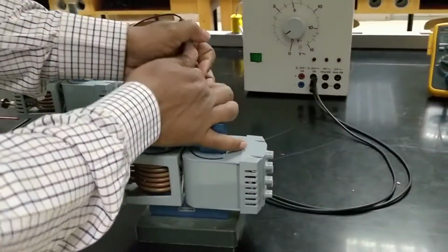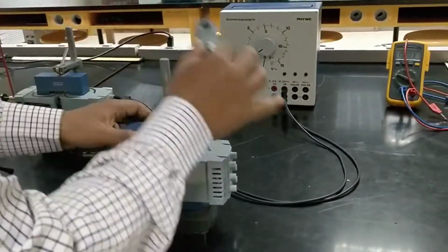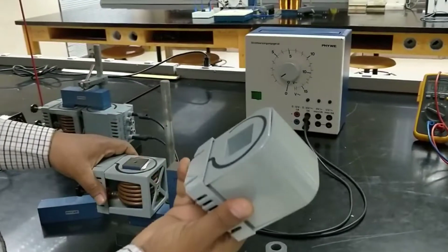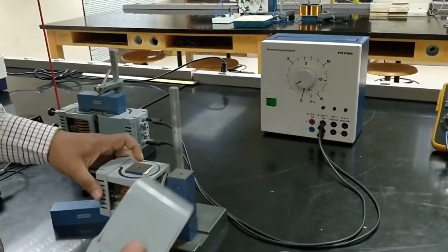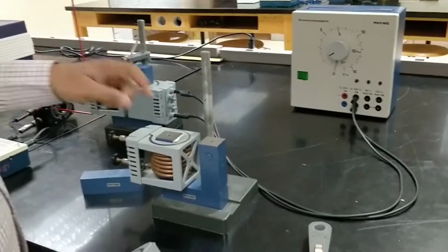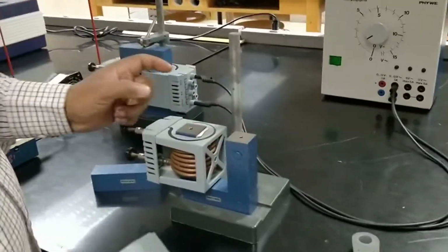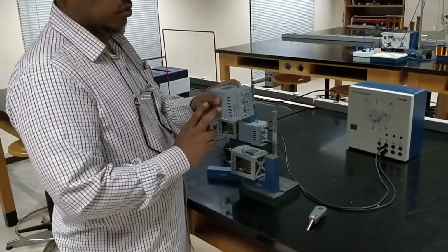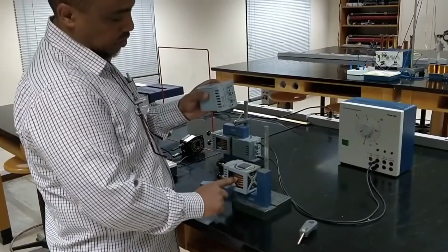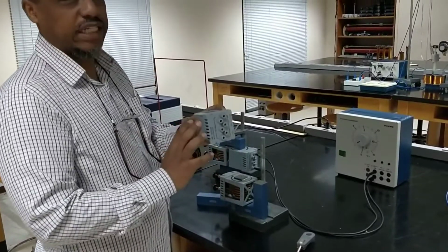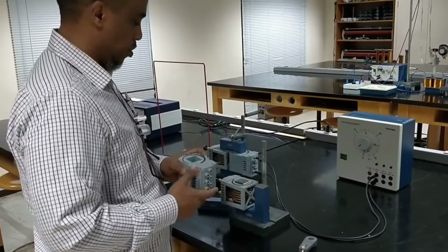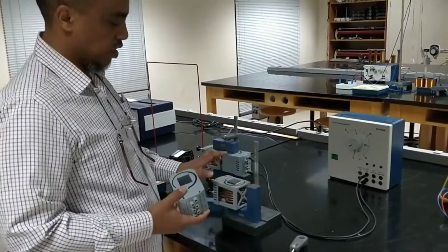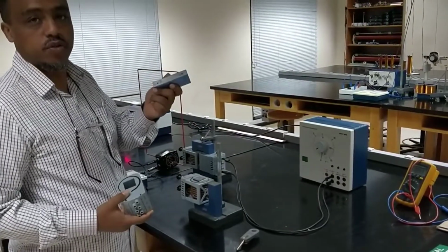Basically, it is made of two coils. This is one coil and this is another coil. Nothing is connecting them except this core, which will connect the magnetic flux that was generated due to the current passing through this coil into another coil with no electrical connection. The connection will be only through the magnetic flux that will be passing through the core that we have here.